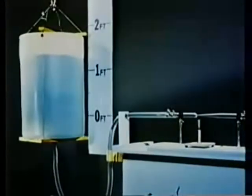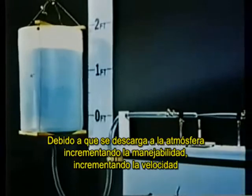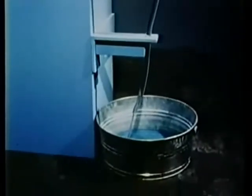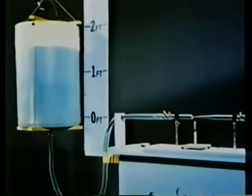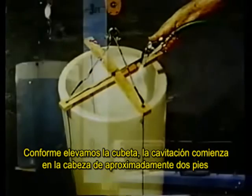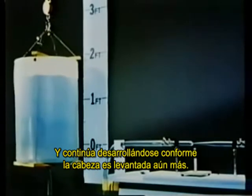Now, even a stable nucleus can decrease in size and eventually disappear because its gas content may diffuse into the surrounding fluid. We can show this with the Venturi experiment by comparing the cavitation inception pressure for freshly drawn water with that for water which has rested undisturbed for some time. Because the discharge is to the atmosphere, increasing the driving head increases the velocity and thereby reduces the static pressure at the throat. This bucket is freshly filled with tap water. As we raise the bucket, cavitation begins at a head of about 2 feet and continues to develop as the head is further increased.